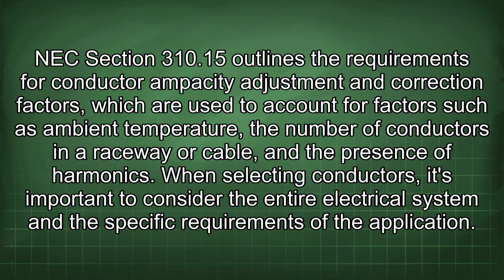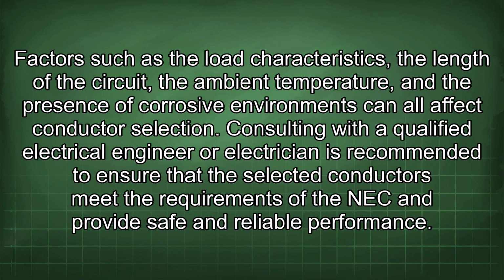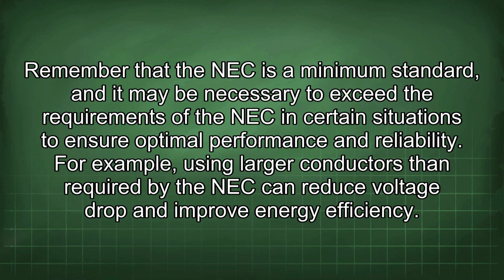When selecting conductors, it's important to consider the entire electrical system and the specific requirements of the application. Factors such as the load characteristics, the length of the circuit, the ambient temperature, and the presence of corrosive environments can all affect conductor selection. Consulting with a qualified electrical engineer or electrician is recommended to ensure that the selected conductors meet the requirements of the NEC and provide safe and reliable performance. Remember that the NEC is a minimum standard, and it may be necessary to exceed the requirements of the NEC in certain situations to ensure optimal performance and reliability.